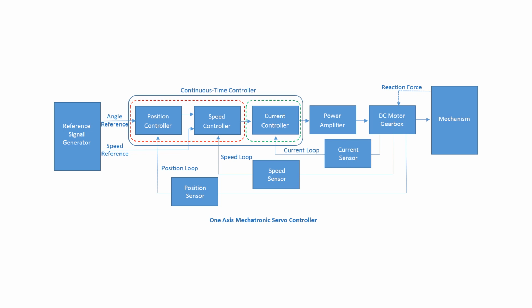We have developed a proportional integral controller, PI, and an integral controller, I. We will use the integral controller in this case. Speed loop: it controls the rotational speed of the mechanism. In our case we want to develop a proportional integral controller, PI. Also, because we want to control the joint's maximum acceleration, a speed reference signal with an adequate speed profile is needed. This will be part of the signal to follow for this control loop.